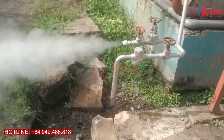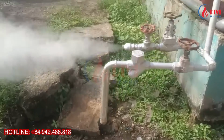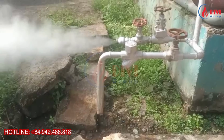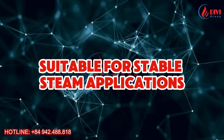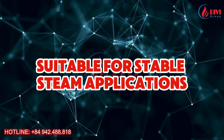Another advantage is that it can produce drier steam when the steam space is properly designed. Because the steam space is larger, steam velocity above the water surface is lower, reducing the chance of water droplets being carried into the steam line. As a result, this design generally provides better steam quality for applications that require stable dry steam.